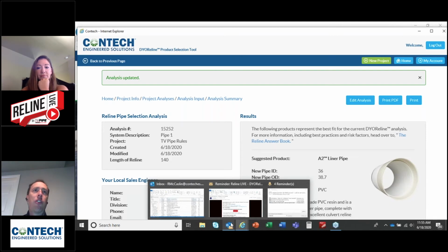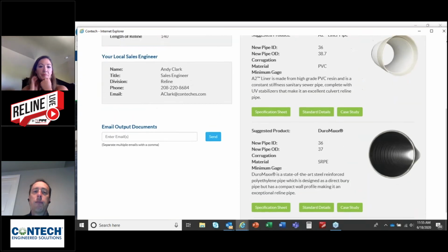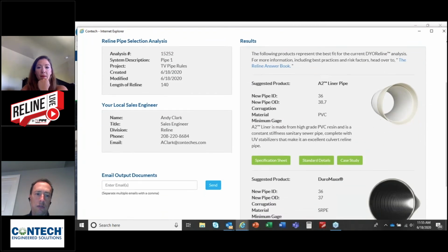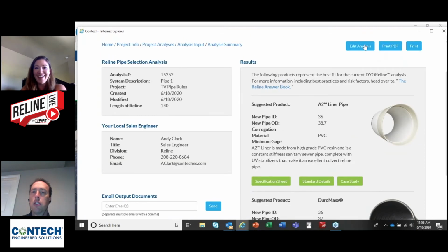And the other instance I would say is definitely use water is if you're bringing in, let's say this is a direct bury application, if you're bringing in soil to backfill around the pipe. And that just made me think of the actual better answer is, since we are backfilling with a grout, soil will never come into contact with this, so you should only use your water. So I had a little bit of brain fart there, everybody. Sorry about that. Your water pH should be the answer for that. Okay, let us know if you have any further questions on that.